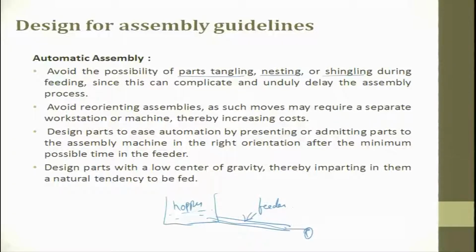So, what we have to do is, when we are trying to push the parts from the hopper, the parts might get tangled, the springs might get tangled. So, you try to make sure that the parts are not getting tangled, nesting does not happen, shingling does not happen during the feeding, since it can complicate and unduly delay the assembly process. Avoid reorienting assembly, as such moves may require a separate workstation or a machine, thereby increasing the cost.